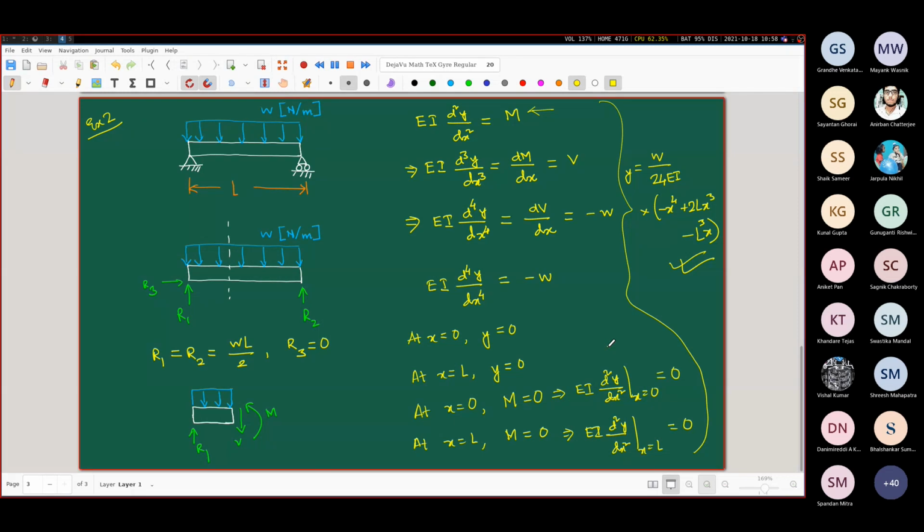Rather, some professional engineers use catalogs or handbooks where various fundamental solutions to these easier distributed loadings or easier concentrated forces are listed. And in a real situation, they consider the superimposition of those various kinds of loadings to build up their solutions from those listed solutions. That is referred to as the method of superposition. Another very modern method is to actually code it up symbolically, the kind of things which I have introduced already in my previous tutorial sheets.